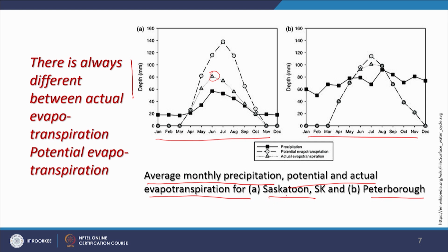of Saskatoon. And what we see here is that when there is less rain in those particular surface conditions, again the potential evapotranspiration was estimated to be more, but the actual also occurred more, whereas the rain has been there. So, the point which I mentioned earlier, and will keep repeating, is that everything depends on local areas, local geology, local topography, local vegetation cover, because one model cannot be implemented for another or replicated for another. The two examples which we are seeing are from foreign countries, but nonetheless they show that results are different.